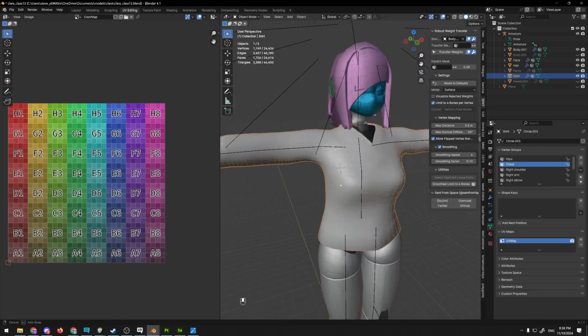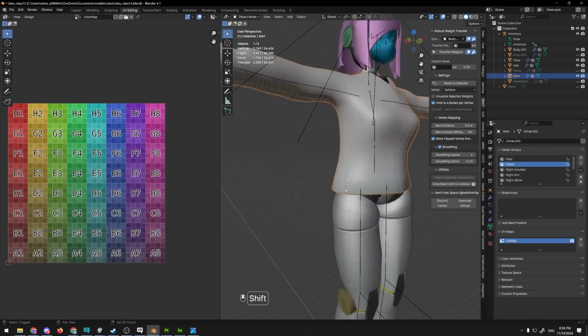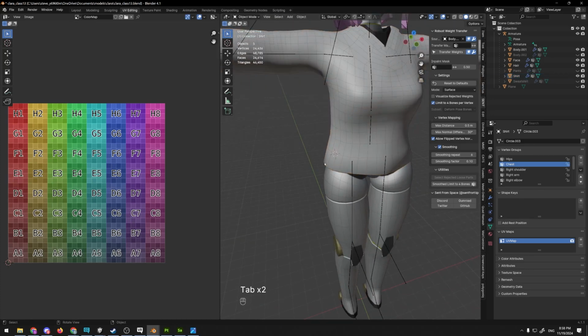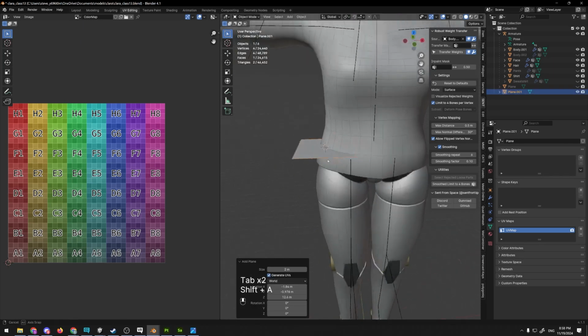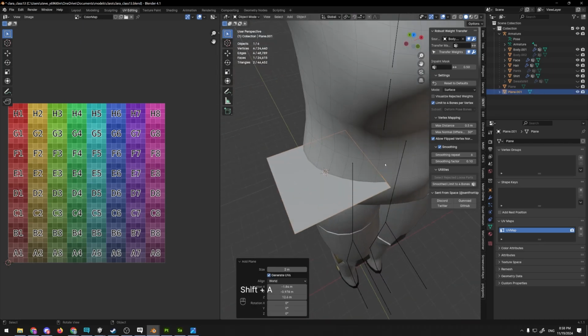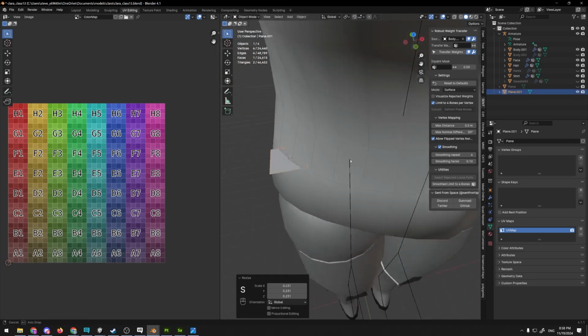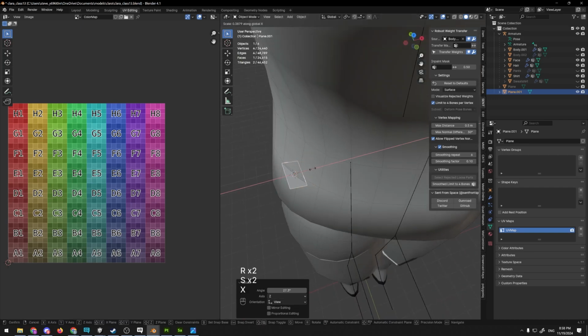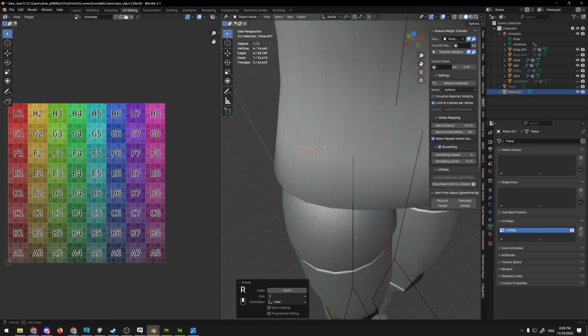So let's say I want to have a strap hanging down from the side at the bottom, right? So I can put my 3D cursor by shift right clicking wherever I want to place my strap, make a new object. And I'm going to kind of speed run through this process real quick here. But effectively, I'm thinking just like a small 3D strap, right? So I'm going to make a cube. I'm going to rotate my cube. I'm going to scale it to kind of be more representative of a real strap. Place it about where I think it should be.